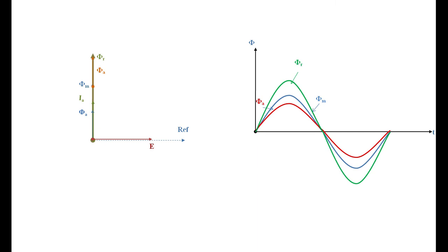Means in toto, that is in the case of the synchronous generator, the effect of the armature reaction is for resistive load, a cross magnetizing effect. For lagging load, it is a demagnetizing effect, whereas for a capacitive load, it is strengthening the main field. It is aiding to the main field, strengthening of the magnetic field. Okay. With this background, in the next session, we will draw the equivalent circuit diagram of the alternator.